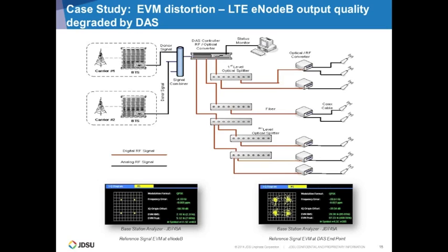This is a simple case study where we've actually seen, as we were demonstrating one of our products, the customer getting very excited about what they could see as far as visibility, again, back to testability of a BTS. All of a sudden they stopped and they paused and looked at me and said, "Can I also measure the DAS system?" Well, the first concern I had was, is it a neutral host? He said, yeah, but it's a stadium, there's nobody here right now, we can turn it off, we can make a connection into the antennas, and we have an attenuator so we're not damaging the test equipment, and we can look at what's coming on the other end of the DAS.